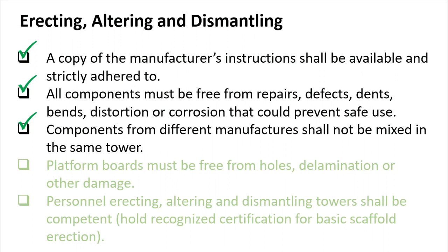Then what will happen to the existing mobile scaffold? It might collapse because of the lower safe working load of the bracing or the components. So never mix any components of different manufacturers.